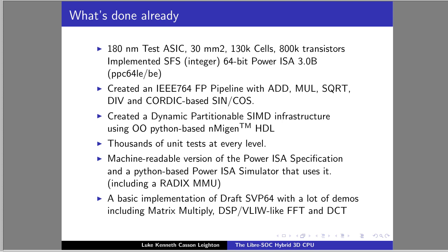Then, as this advanced, and we added an MMU and level 1 caches, we had to actually add a Radix MMU to the simulator, and we used the Gem5 Power source code and QEMU's Radix MMU source code as reference, as well as the Microwatt HDL, Microwatt VLSI.